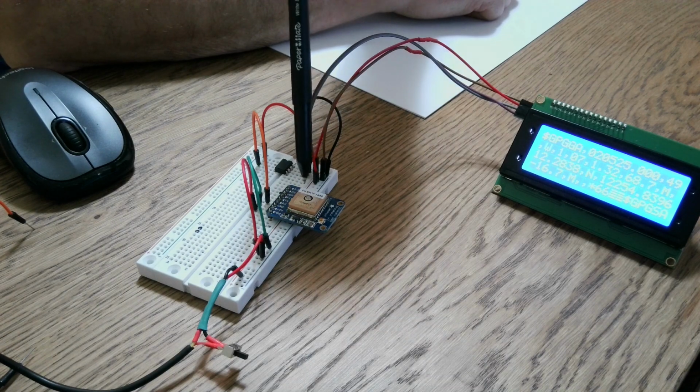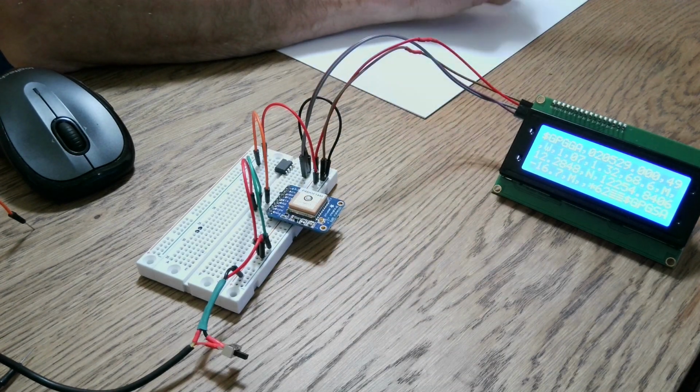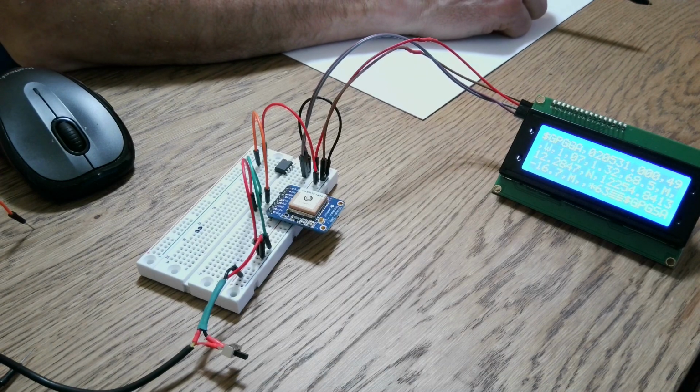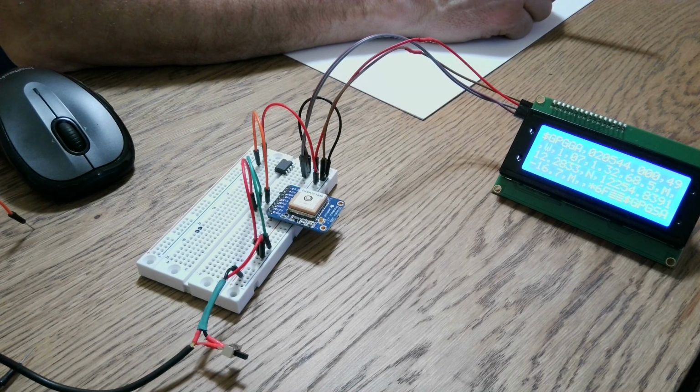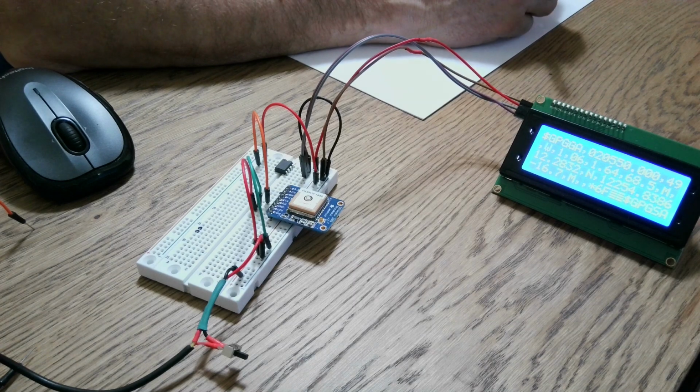Coincidentally, the GPS module, when I plug in the power, it instantly starts sending data. I don't have to actually communicate to it. It just sends out a stream of data once every second, and roughly 200 milliseconds worth of data. And then it stops for about 800 milliseconds, and then it sends out another stream of data, it sends out this right here.